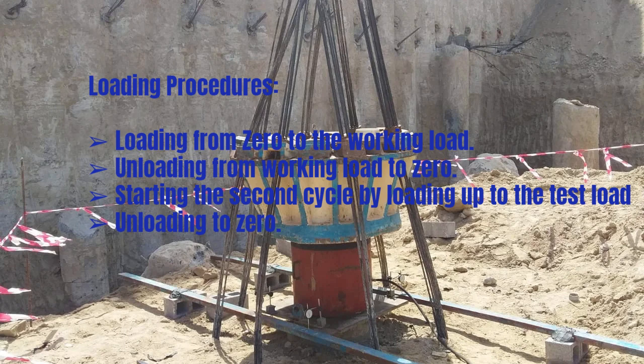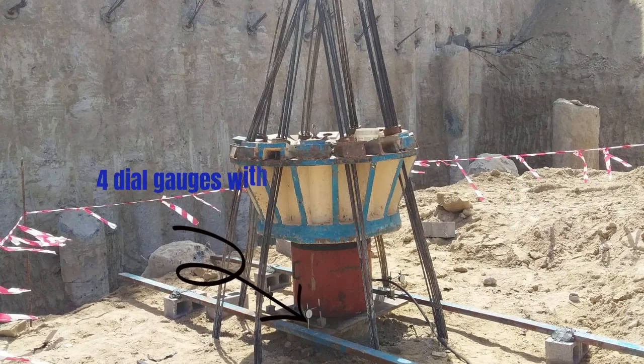Reference beam and dial gauges. The measurement of the pile head movement shall be made by 4 dial gauges rigidly mounted on the reference beam. The tip of the gauge shall bear onto a glass or other smooth plate glued to the prepared pile head and normal to the pile axis. The dial gauges shall be placed equidistant from the pile axis and from each other.